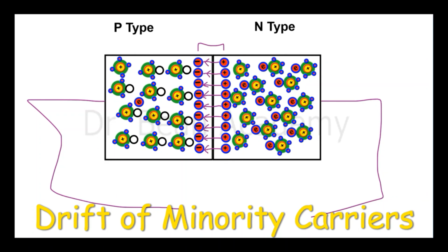And even in the reverse bias, I told you that you will see a little current, and that current is because of the minority charge carriers. Not because of the majority, but you can see some current. And still the reason of that current is the external voltage you have applied to the P and N type side of the PN junction diode. But the drift current is different.